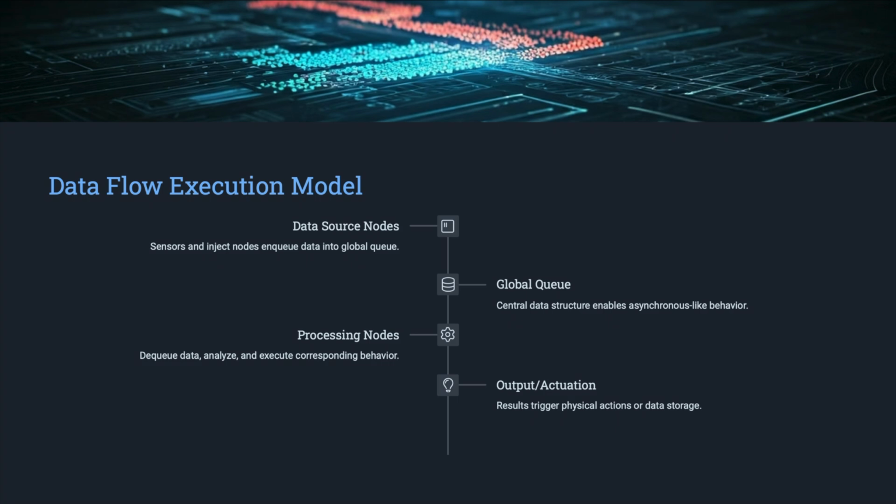No, not on these devices. When the Ruby code hits a sleep, especially in the main loop when the queue might be empty, it tells the microcontroller's hardware to go into a deep sleep mode. Low power state. Extremely low power. The CPU basically shuts down most of itself. Yeah. It only wakes up when, say, a hardware timer interrupt fires, like the 1-second timer going off, or maybe another signal indicates there's something new to do, like a new packet just got enqueued.